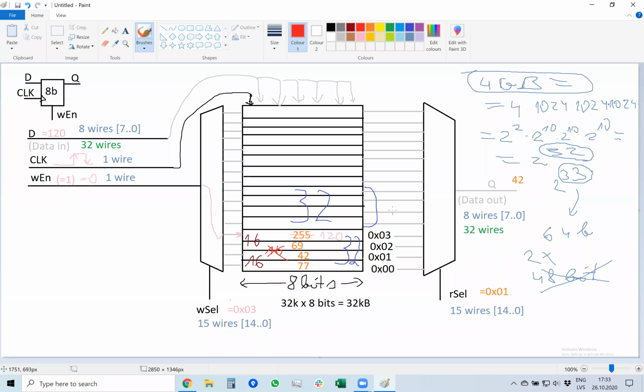But you cannot store a 32-bit number in addresses that start with some odd number, 1, 2, or 3, or 5, 6, and 7. So you cannot, for example, store it like this, because this address will be 4, this will be 5, this will be 6, 7, 8, 9, and so on. So this way it would be stored in addresses 6, 7, 8, 9. 6 does not divide by 4, so it's impossible.